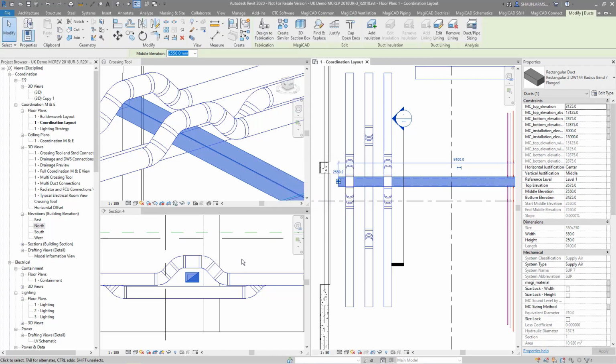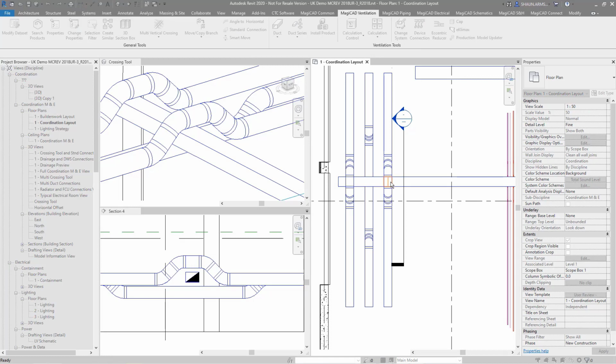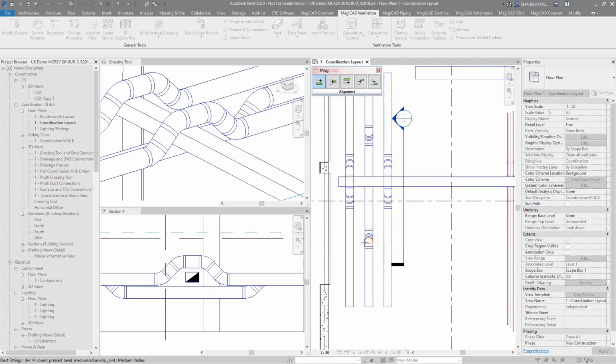So now my offsets are changed. The 100mm offset that I previously had is not there any more. Using the Smart tool, I can readjust that offset from the insulation that has now been added. I have been given the height of that duct there, so I'll select the right duct. And then I can reuse my offsets: on top of, at center of, at bottom of, top of top, and then bottom of bottom. I can use all these reference offsets to re-reference my duct.